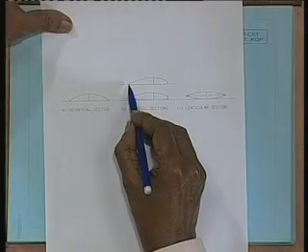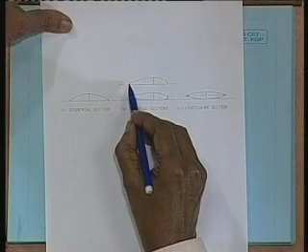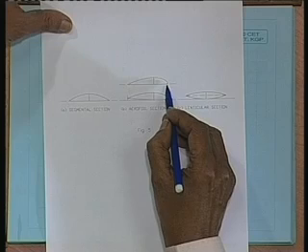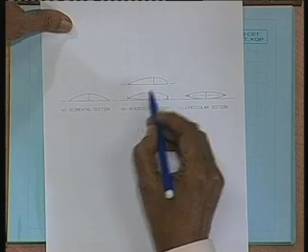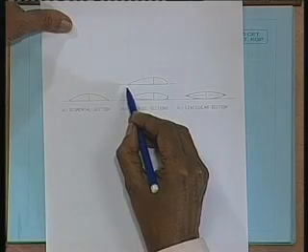Shape is known as aerofoil section, where you can see the leading edge is not really sharp, it is rounded, and the trailing edge is sharp. That is how propeller blades are made. The leading edge has a curvature, but the trailing edge is sharp. That is another way of knowing which is the leading edge. The one that is sharp is the trailing edge, the one that is blunt is the leading edge, and that is the one that will be meeting the water first.